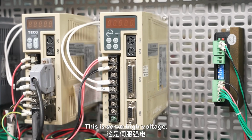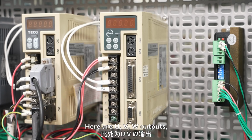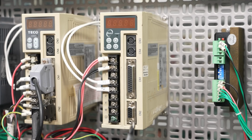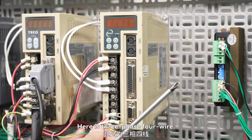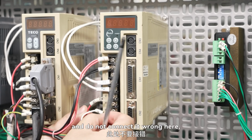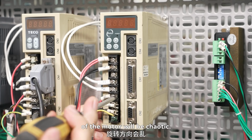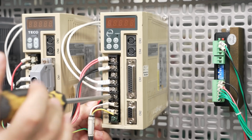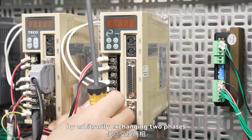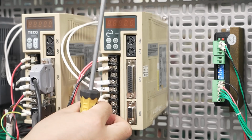This is servo high voltage. Input servo. Here are U, V, W outputs directly connected to the servo motor. Here is three-phase 4-wire. The U of UVW is connected to U1, and do not connect it wrong here, otherwise the rotation direction of the motor will be chaotic. The sequence can be converted by arbitrarily exchanging two phases among the three phases.